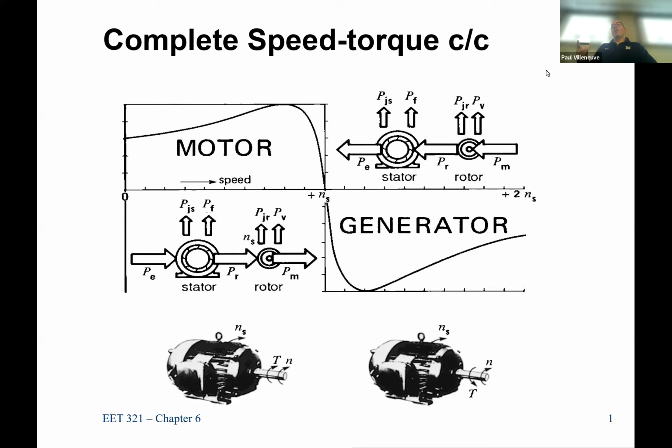And once it's up and running, as long as it has enough inertia, it will start to slow down, but it's able to keep the voltage up because, again, it's a synchronous machine. It doesn't need voltage support. It provides its own voltage support. So as that synchronous machine is spinning down, it's able to keep the grid voltage up. Okay. So you'll see some of the wind projects in Western Maine use synchronous condensers to provide voltage support.